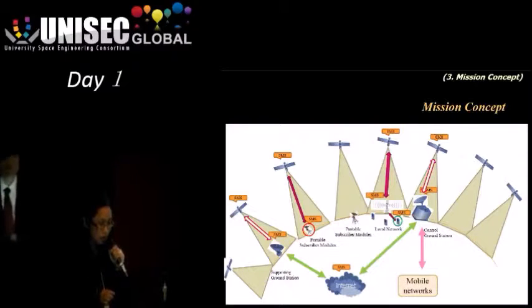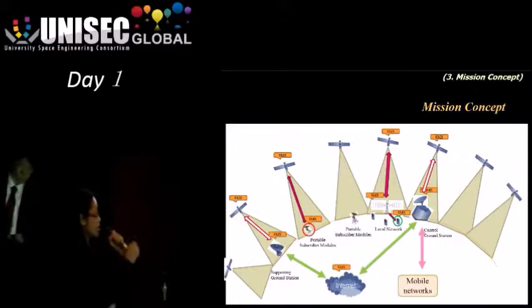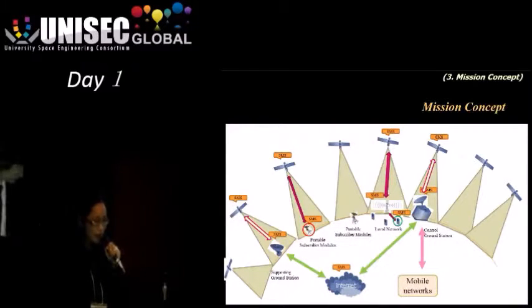Say, for example, we want to send a message from user red to user green, here encircled. When the satellite passes, you can send data to the satellite. Then this satellite will pass this data to the nearest supporting ground station, which will send it via the internet to the control ground station. Then the control ground station will send this data through our network until it reaches the desired local network, which then transmits the data and reaches the subscriber.